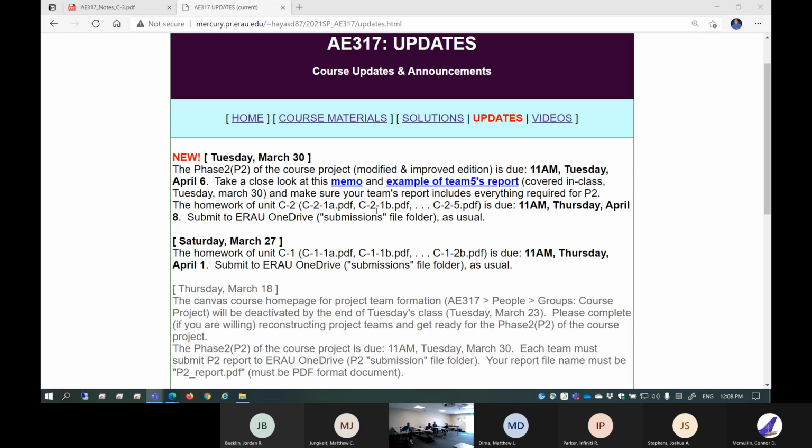And then, of course, how much fuel do you need? Where do you put your fuel comes in, okay? Now, suppose you put your fuel in the very back of the fuselage, that could potentially make your airplane completely unstable. So you have to double the size of the tail. So major configuration change may happen at the stage of stability analysis, okay? So at this moment, your airplane's basic configuration comes into play. Based on that, you're going to choose your power plant, and you'll try to integrate the power plant, and then plot thrust or power curve. And out of those things, you're going to compute performance.